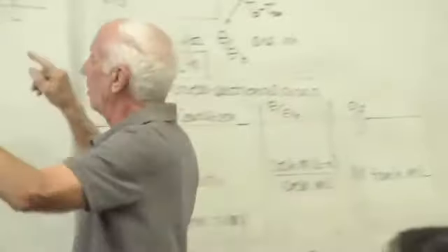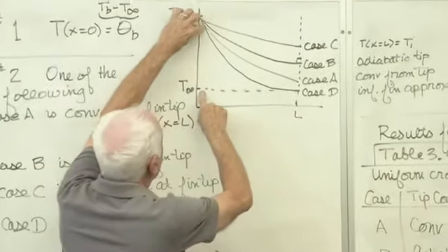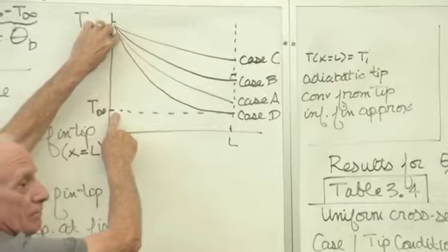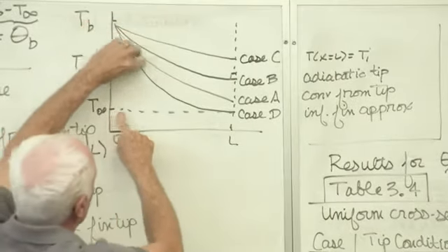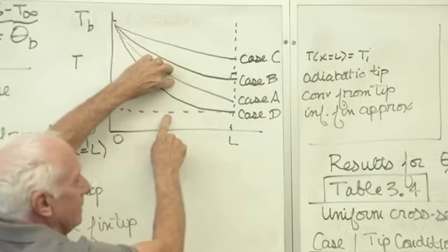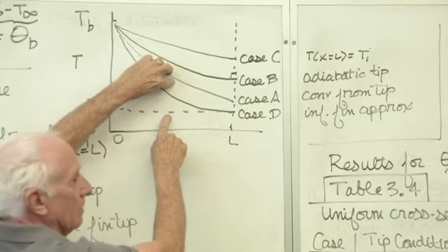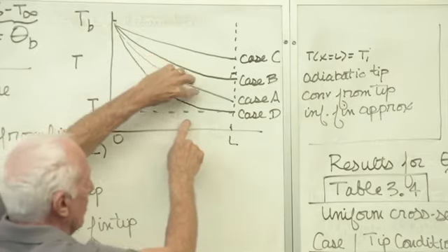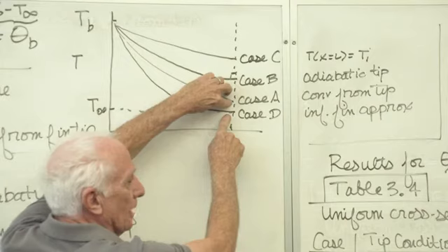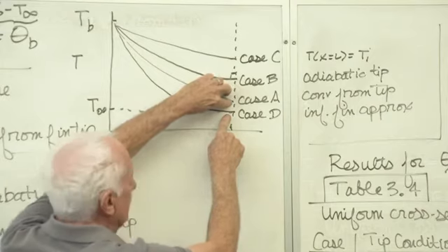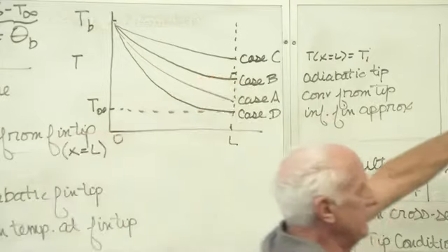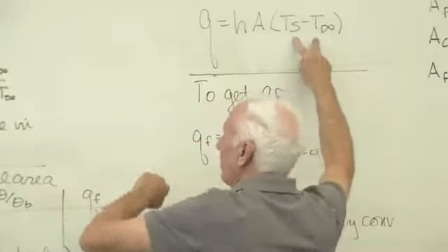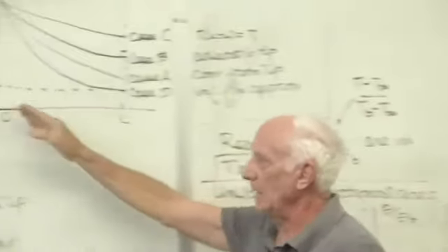Close to the wall, T_fin minus T infinity is really, really big. Go halfway down, it's getting smaller, less heat transfer. Go out to the tip, it's really gotten small now. This heat is going down and down as we go from the base out to the fin tip.